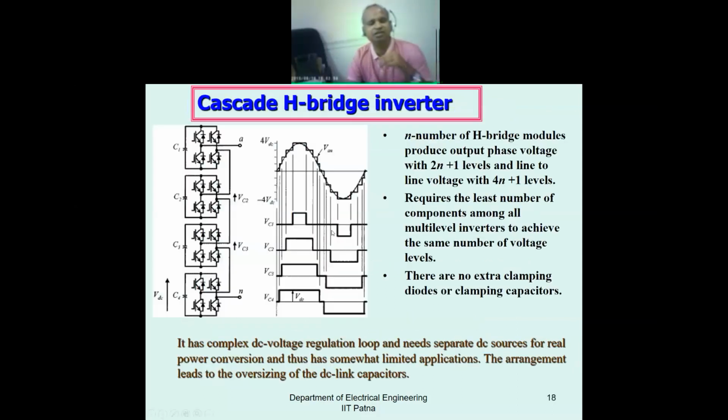This is also another cascaded N-level converter you can realize. So this way we get the cascaded inverter. If you add each level from each device, you will see that it becomes a simple sine wave. This is the cascaded output.